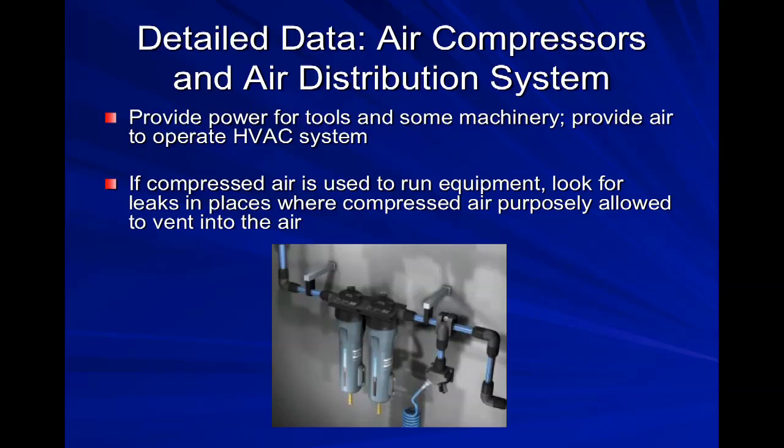Air compression systems are quite often huge opportunities for energy management opportunities. Quite often you'll have a leak near a piece of equipment that has a built-in leak. When it's operating, air is going through and it's doing some work and it has to be exhausted. Well, while it's exhausting, we may not notice that there's also another noise present that is an unintended leak. And these, as we'll see later in the book, can add up to some significant losses and costs for the company.